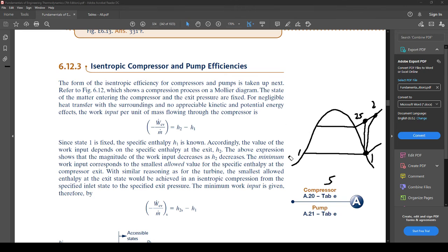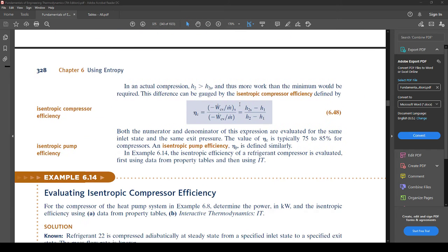Now, really fast, this is why I wanted to show this one, because this is where people often get confused. So when we look at the efficiency of a compressor, right here, what you will notice is what? What has flipped on this one? Can anybody see on this equation? What has flipped? Yes, so the numerator and denominator have flipped. Essentially, the bottom now is the maximum work required. The top is the minimum work required, and this was specifically done to keep the value under 1.